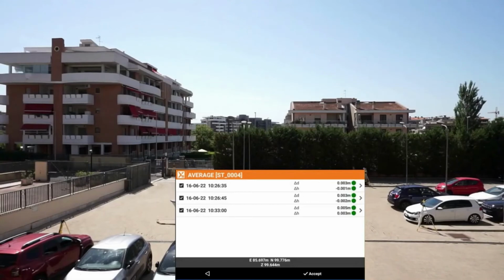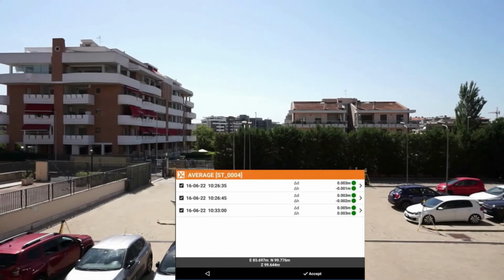So in delta in elevation, distance and elevation, just because we are using a different tripod. So we strongly suggest you to use the wooden tripod and not the aluminum tripod for the traverse, just to have the best calculation in terms of tolerance. Plus, we have to say that this surface is made from small bricks that are floating on sand.